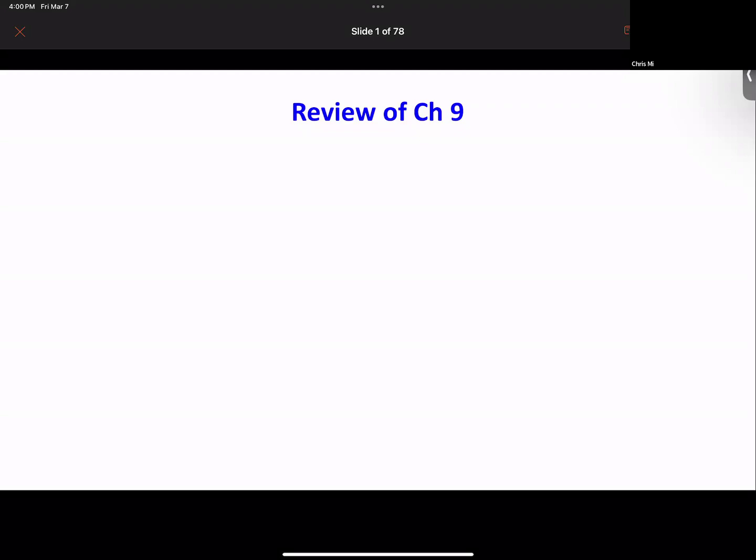Another reason is that with amplifiers, we always have some sort of load. And in the beginning, we always have a resistance at the drain or resistance at the collector. That's your load resistance. But later on, as we said, we don't want to use that resistance. And what do you use? You use another current source. When you have a current source, basically the ro of that current source becomes your load resistance. So that increases your gain and eliminates the use of that resistance. So that's why you have a current source.